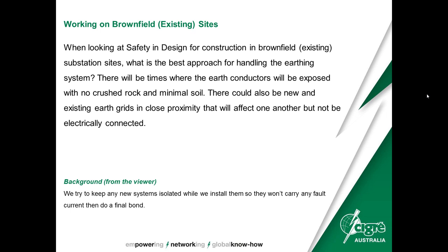You go back to the major supply sub in that same mine and it won't be fault limited and it will have much higher EPRs and higher currents. You've got to decide one of two approaches really. You either are going to become equipotential bonded and you're taking a bird on a wire approach, or you're going to be separated from that voltage rise, the EPR that could occur during a fault. However you do that,